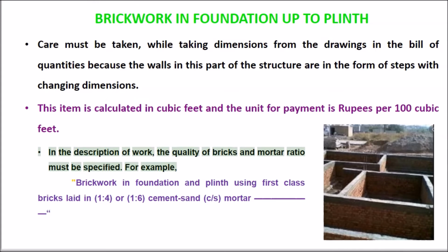In the description of work, the quality of bricks and mortar ratio must be specified. For example, brickwork in foundation and plinth using first-class bricks laid in 1:4 or 1:6 cement sand, CS, mortar.